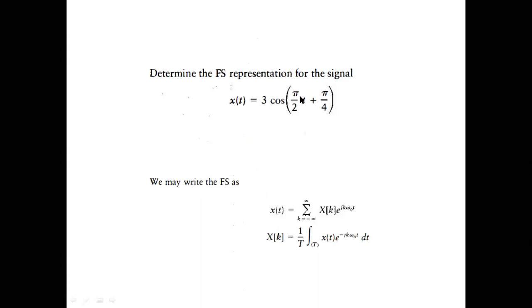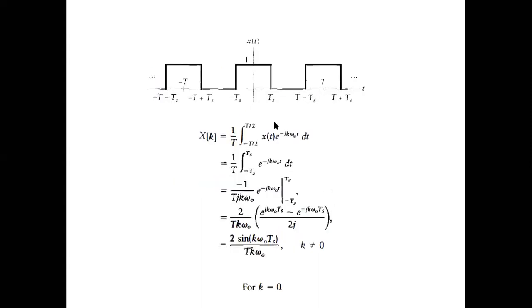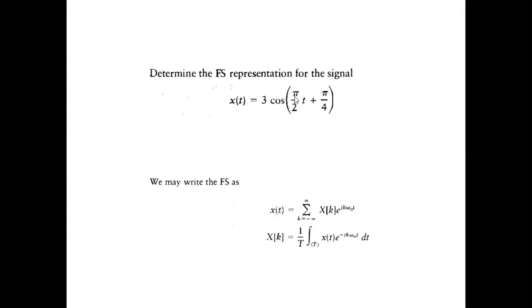Earlier, we substituted in the formula. If you are given any kind of random wave which is periodic, you just have to find the period, find the fundamental frequency, substitute, and go on doing the integration till you reach a certain value where you can plot it. That's it. Now this is a typical question where you know there is only one frequency which you need to identify.